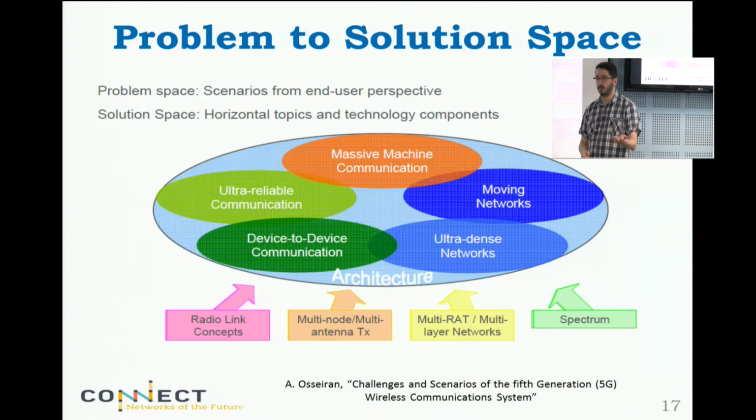To name a few, GFDM, filter bank multi-carrier. GFDM stands for Generalized Frequency Division Multiplexing. Filter bank multi-carrier, FBMC, is another one. Then you have Universal Filtered Multi-Carrier, UFMC. They are all sort of related, but they are all different. So depending on what you want to get, you will pick one or another. But what they have in common, generally speaking, is looser synchronization requirements compared to OFDM.